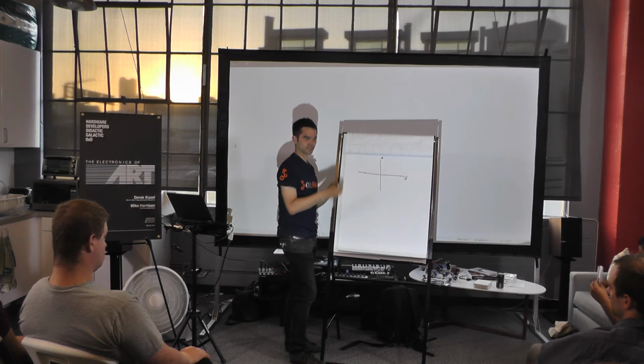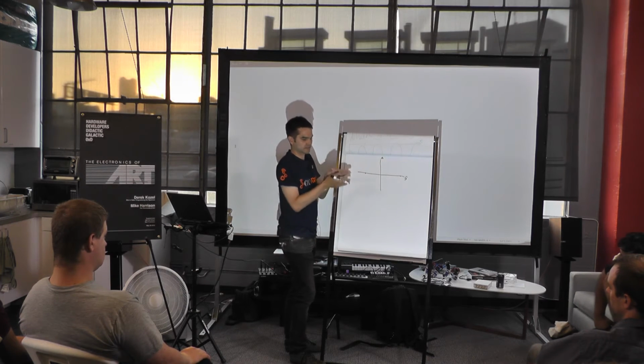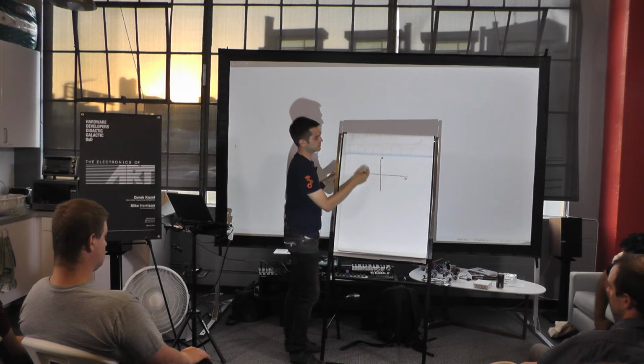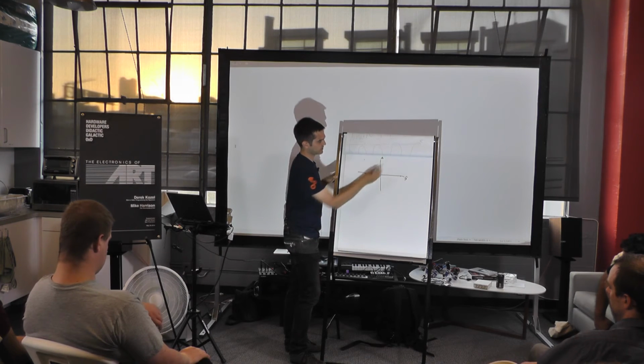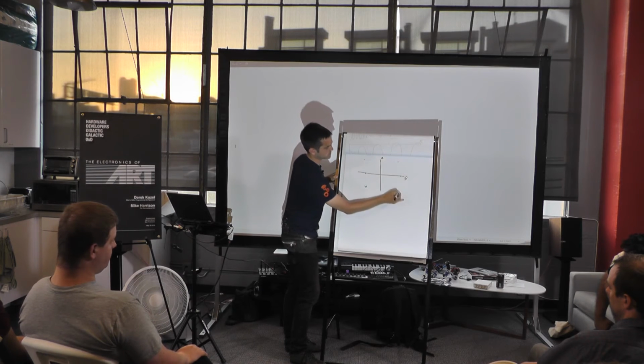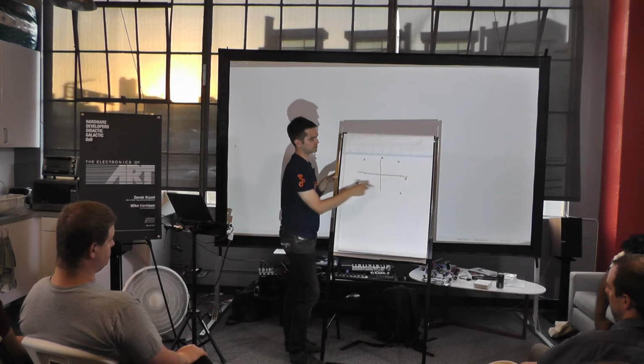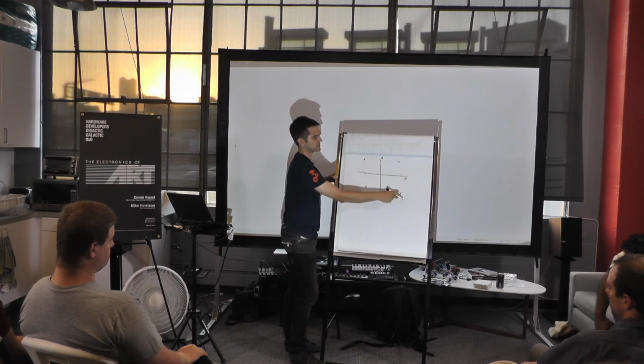Well, what if we also said, okay, you can transmit the really low frequency, but you could also have it low amplitude or high amplitude. You'd have another data point up here, and there, and there, and there. I'll go with X's for these ones. So now we're able to send 2 bits of data for each sample period, because you can be at each one of these constellation points.